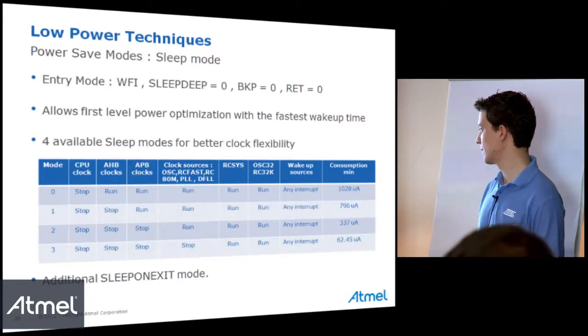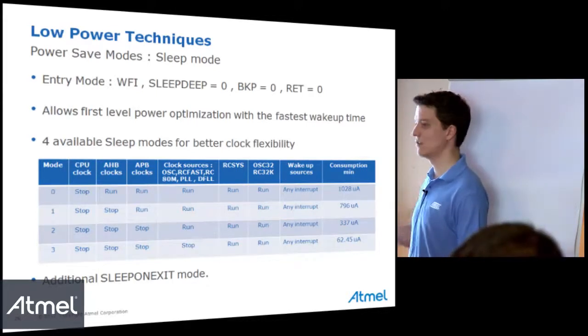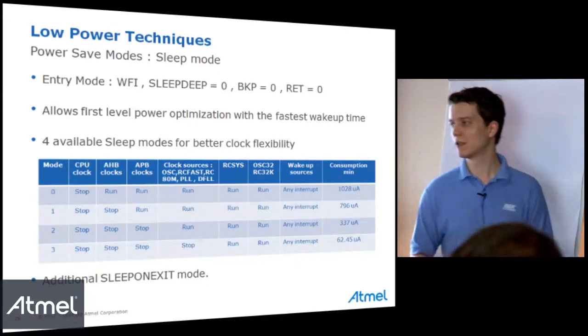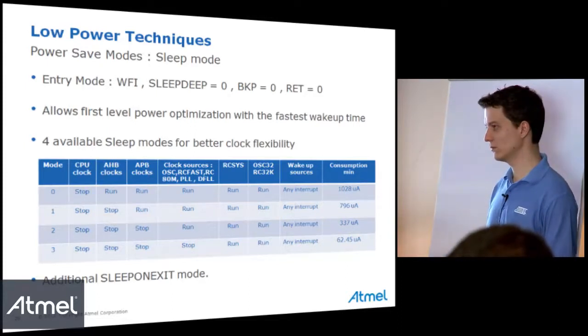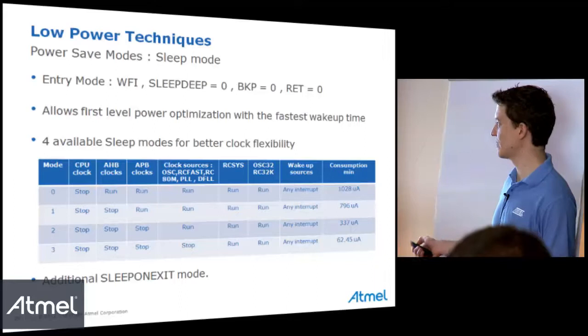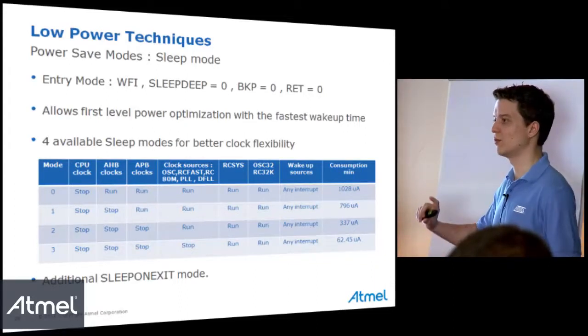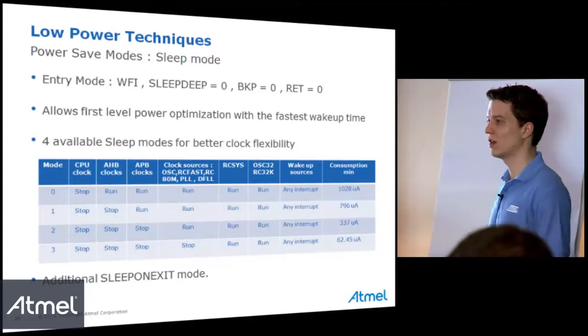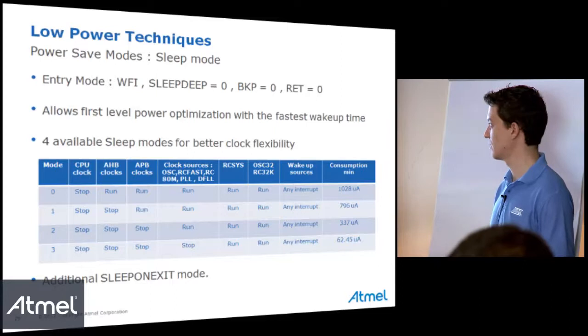Ah, yeah, okay. In sleep mode, they enable it, even if it's not selected, they still power the PLL. Okay, you're running at max frequency. So that's the reason you see this. Yes, you're right, and that's the reason that we have the fastest wake up time, because we have a mechanism that switches directly to the maximum clock frequency.